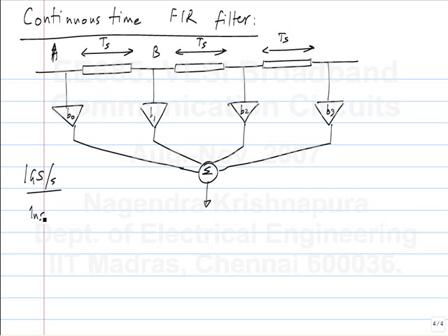Is there some idea? Okay, what is the speed of the wave? Assume something. Speed of what wave are we talking about here? Speed of light. Okay, so let's say it is the speed of light in vacuum, or air. What is the length you need? 0.3 meters. So the speed of light is 300 meters per microsecond or 300 millimeters per nanosecond. So to make 1 nanosecond delay, you need 300 millimeters.